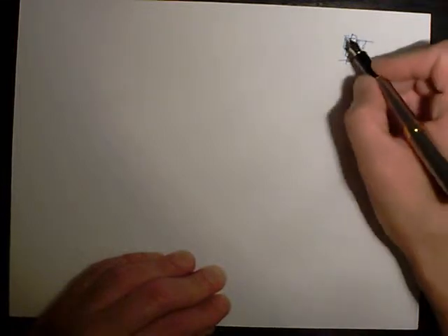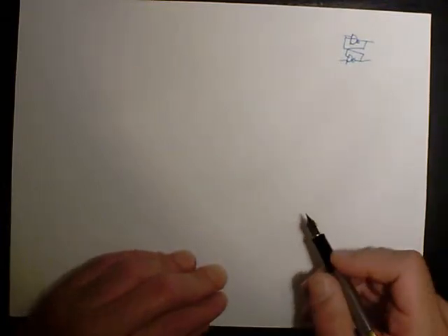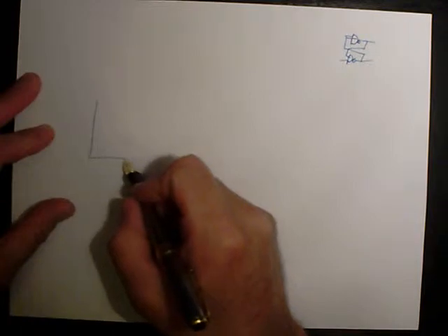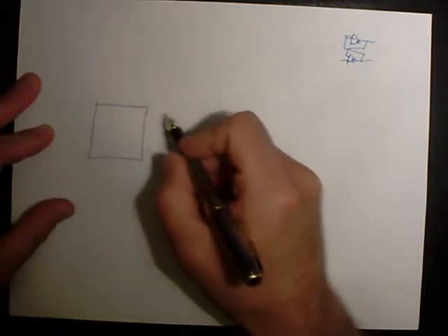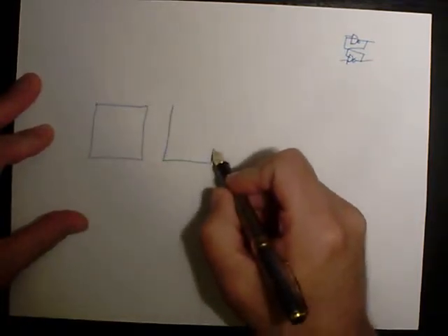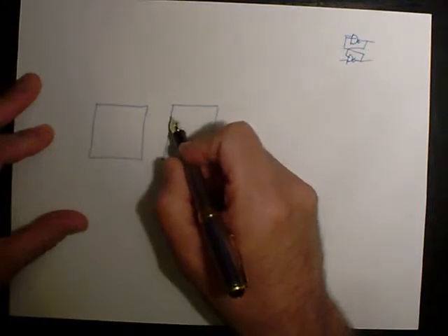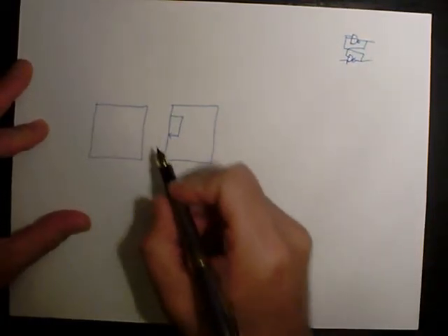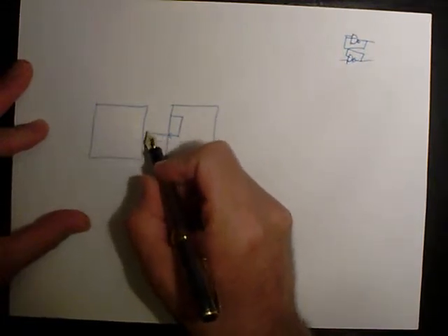And that's fine, but it's actually a bit of overkill because the individual cells of a cell matrix can do more than simply act as a two-input gate. So here's a strategy we can use to implement, for example, a D latch. So we're going to have two cells. The cell on the right is simply going to circulate whatever value is coming in from the west.